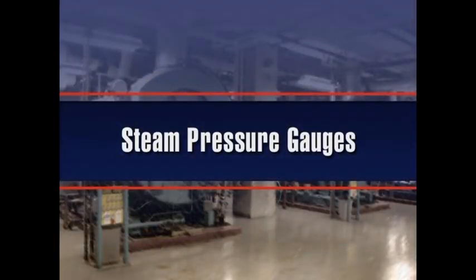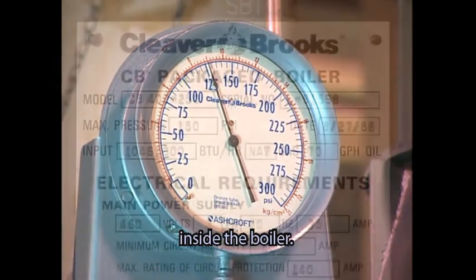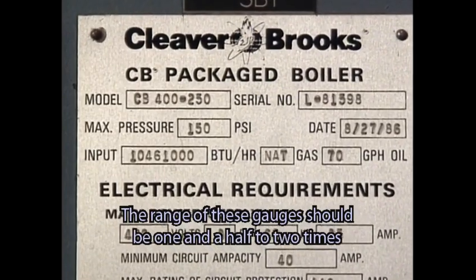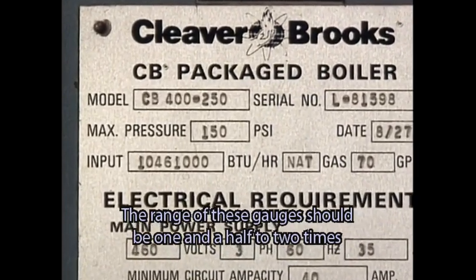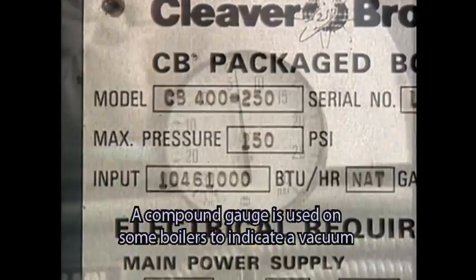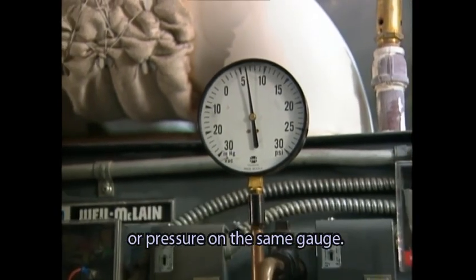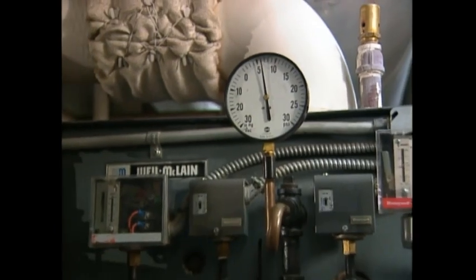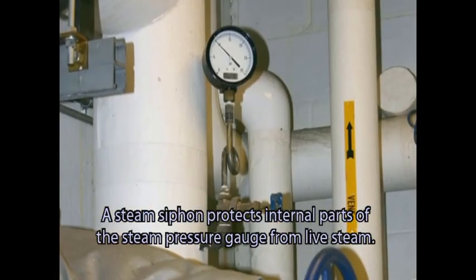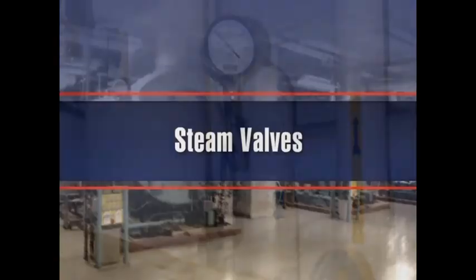Steam pressure gauges. Steam pressure gauges and compound gauges monitor pressure inside the boiler. The range of these gauges should be 1.5 to 2 times the MAWP of the boiler. A compound gauge is used on some boilers to indicate a vacuum or pressure on the same gauge. A steam siphon protects internal parts of the steam pressure gauge from live steam.